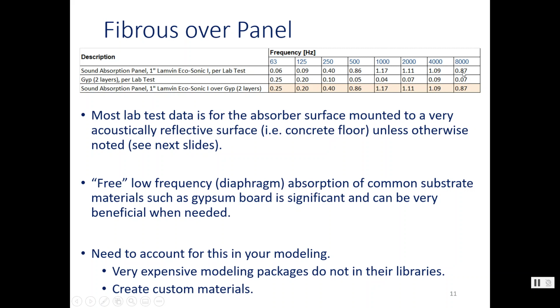So you put that in the model, you switch out the gypsum board for the sound absorption panel, and it brings all that down like you intended, but then you notice that the reverberation in the low frequencies increased. So you add sound absorption panels and the reverberation increases. That isn't what would actually happen.